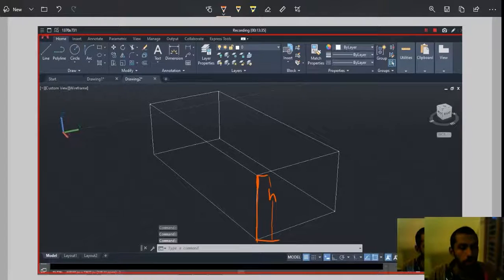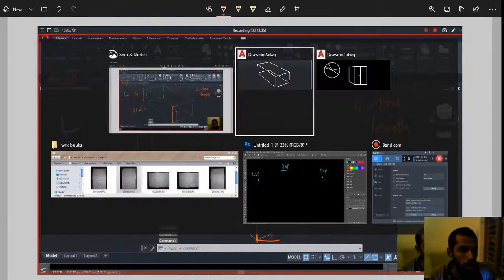As you move away from the camera, h always decreases. If this height is h, then the farther height is always less than h. If you are very close to the vanishing point, h is approximately equal to 0. So that's the simple logic here. The vertical line which is closer to the camera will have the height h, which is called the true length. The first step is to draw the stuff having true length.